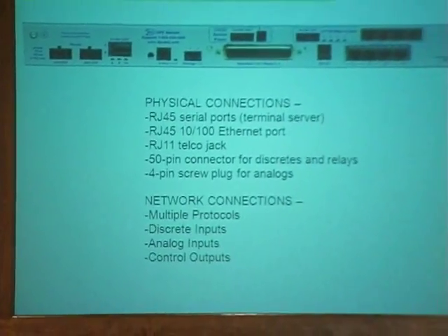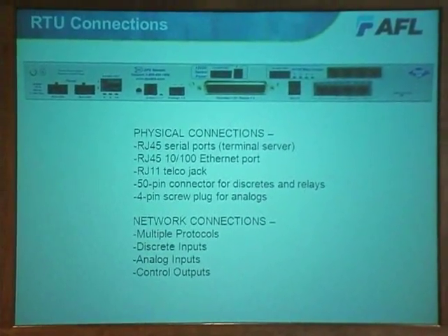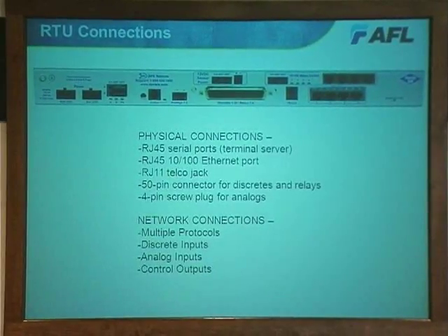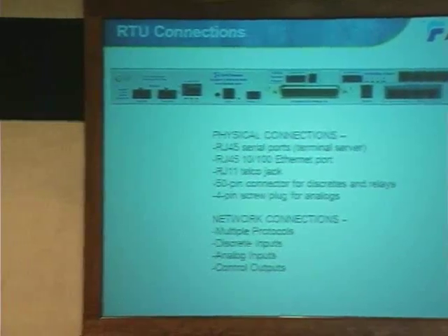Now, if you think about the RTUs, and again, this is getting a little bit lower level here, but to make sure you understand, as I was mentioning earlier in the example for the network services guys out in the networks, you've got all these contact closures to know when somebody's opened the door. You've got the sensors to know what the temperatures are. You've got the alarms coming from the equipment that you're going to feed into this RTU of some sort. This is just one I found a picture of that helped us look through this. And you're going to feed it through these interfaces in the back of that RTU, however it's presented to you.